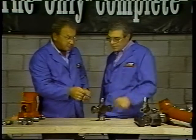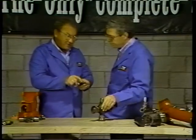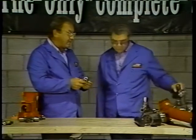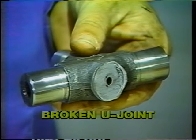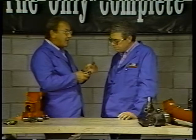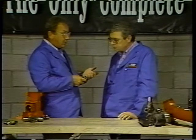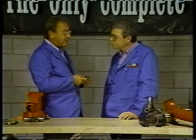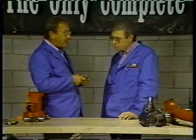Okay. Now, there's another cross failure. How could a break like that occur? Well, this U-joint cross is broken completely. The most common cause of this failure is known as shock loading, or an abrupt, intense shock to your vehicle's drive shaft components. Now, shock loading can occur, for example, when you're spinning your tires and they suddenly take hold. Or it can happen when the driver pops the clutch. Now, as the truck lurches forward, it sends a severe shock through the entire driveline system.